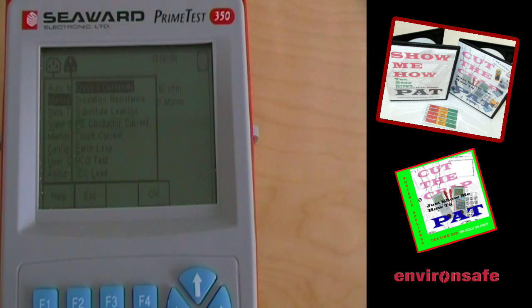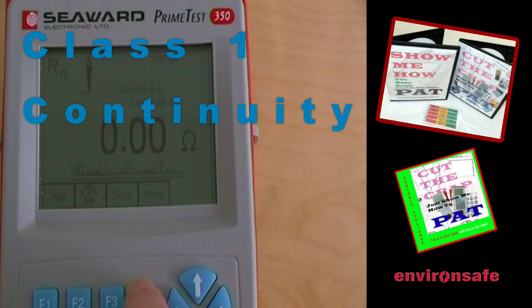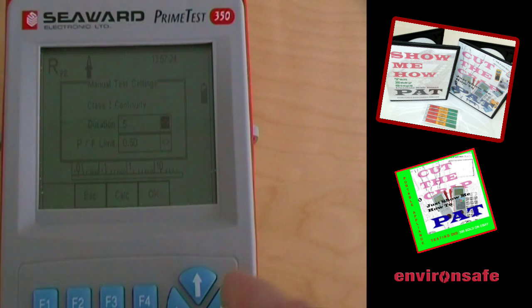Class 1 continuity test. Press F4 to OK that. And the options on that are to zero the resistance, setup, and the class 1 continuity can be set at 2 seconds, 5 seconds, 10 seconds, 20 seconds and 30 seconds. Press the left arrow key to exit that.